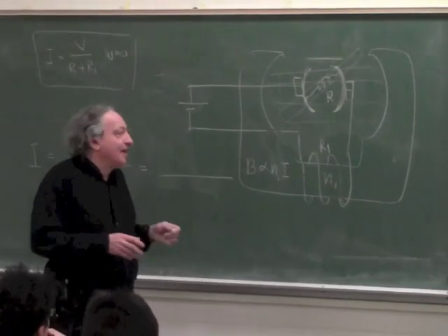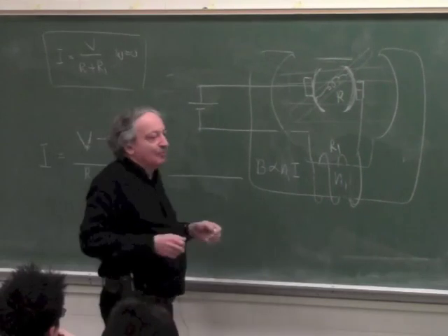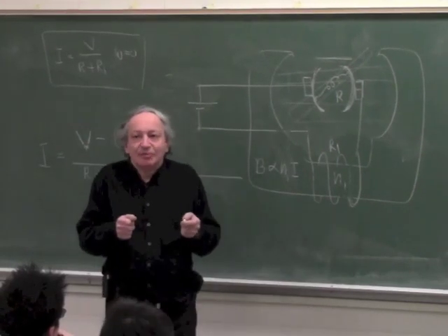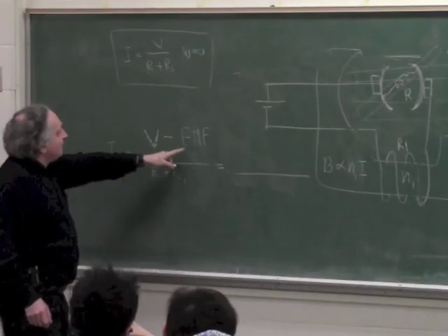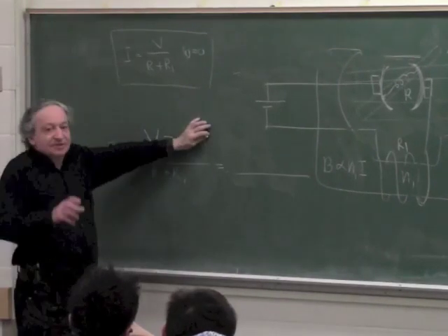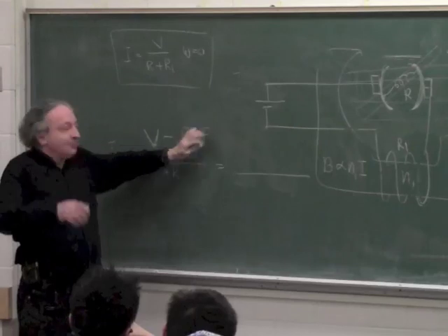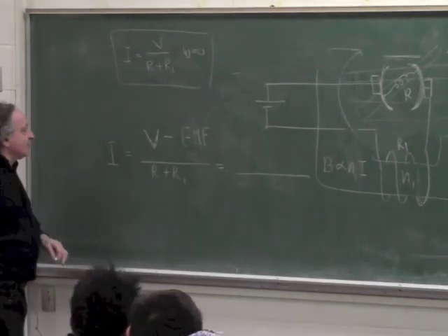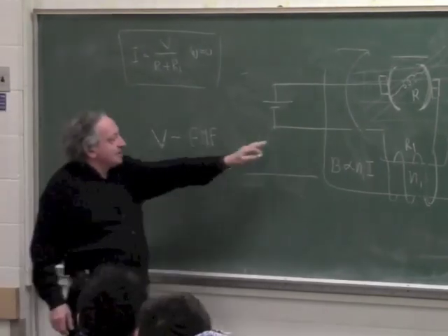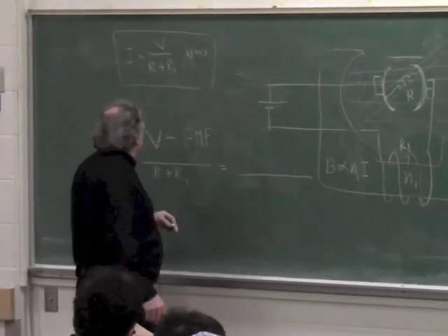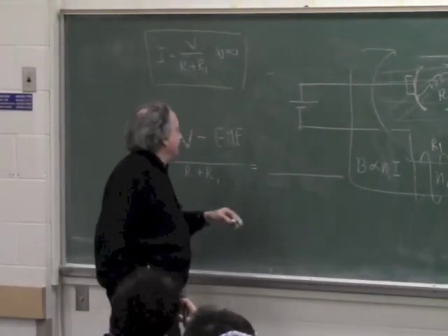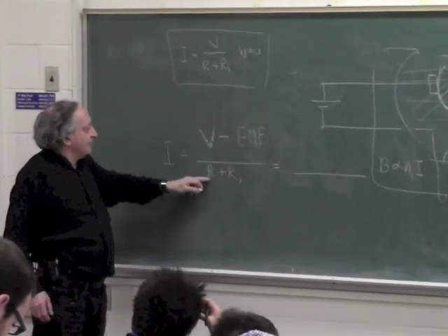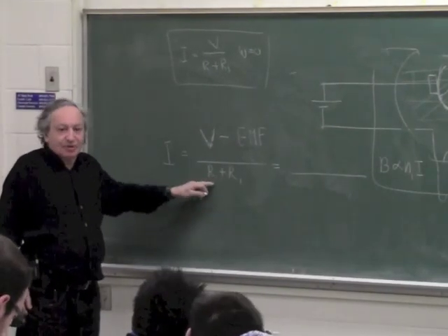Let's say you take this motor and you apply a very heavy load. Then the EMF initially is 0. The motor barely rotates. The EMF is 0, and if the resistances are low, you'll get a huge torque, because the initial current will be very high, V over R, and R is very small.